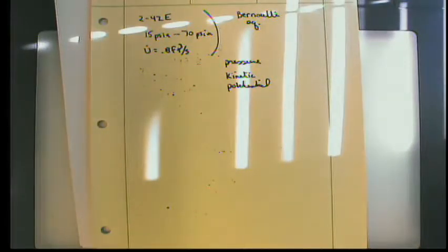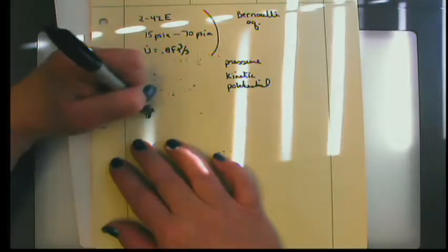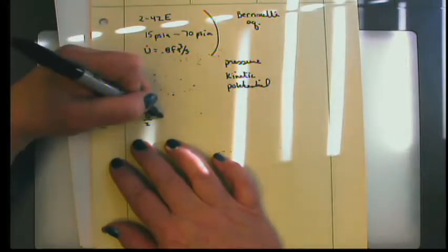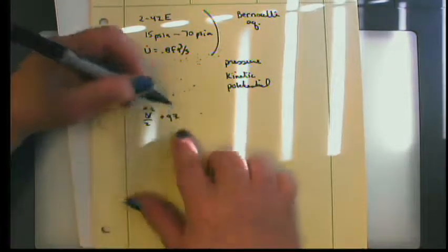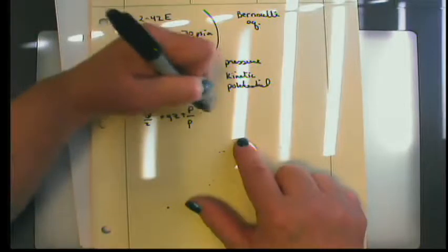There are different forms of the Bernoulli equation, but for incompressible flow like this, they're really based upon the units. In other words, the different forms are just different because of what units we're measuring the pressure in. For incompressible flow, Bernoulli says that v squared over 2, plus gz, which is a position, plus P over rho, is a constant.